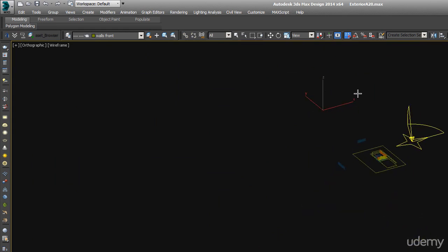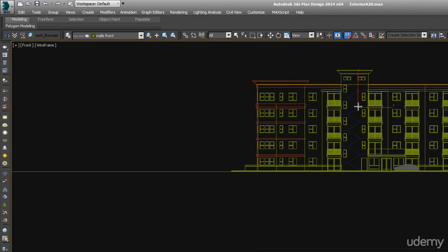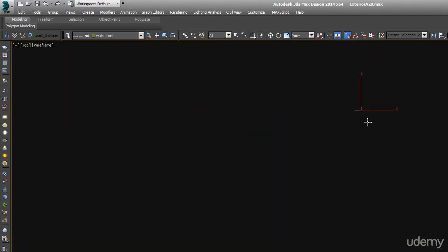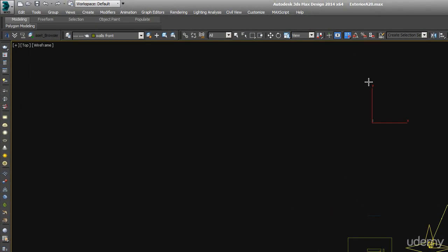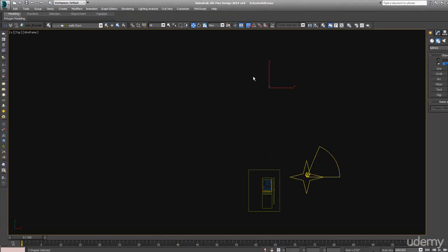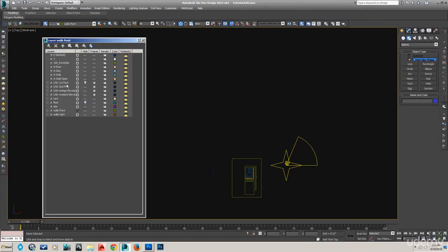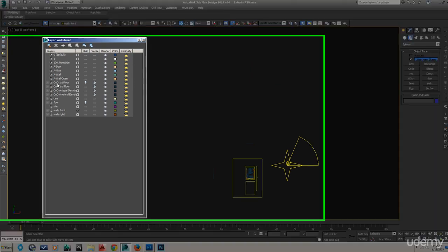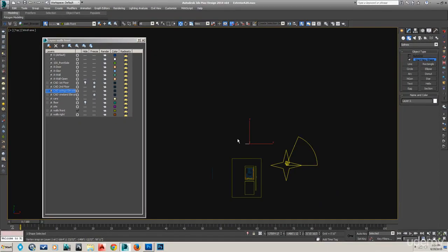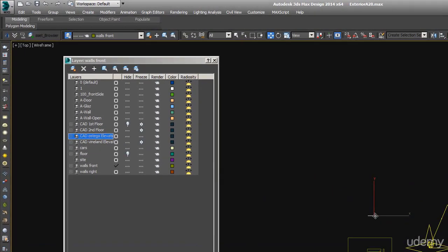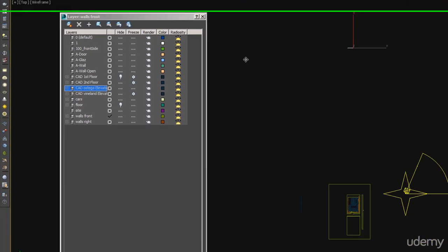Oh. Well, because I have this positioned oddly in space, it's actually still behind, which isn't ideal. If I was doing this correctly, I'd move this all back here so that when I draw this, it will show up in front of my lines, not in back. So there's an easy way to fix that. I can just do, let's delete that. Go to my CAD front elevation, if I have such a layer. Okay, it's that one. And let's move it back in the y-axis, way back like that.